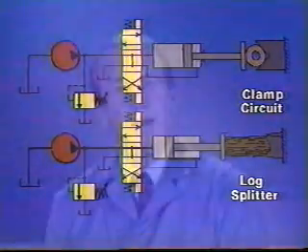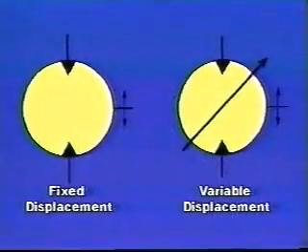When an application such as a conveyor drive, chemical mixer, or injection molder requires a rotating motion, a wide selection of hydraulic motors is available. Here in graphical representation we see two types of motors, one fixed and one variable displacement.